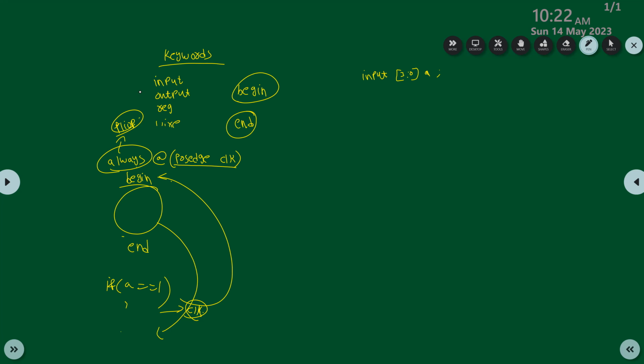So for the specific cases we have, the case statement will be the best solution. Let's say you declare this variable B, which is 8-bit, a selection input. A is the output, and C, D are the other single-bit inputs. This is my requirement, and these are the variables which I declare.